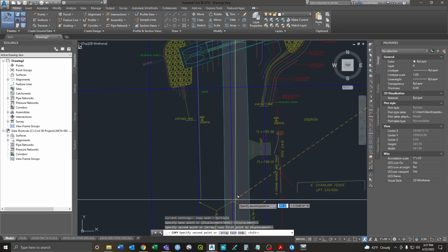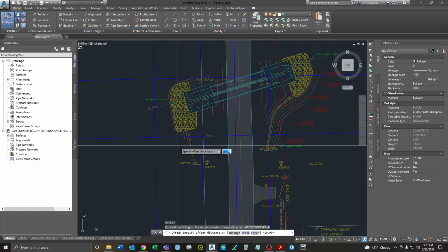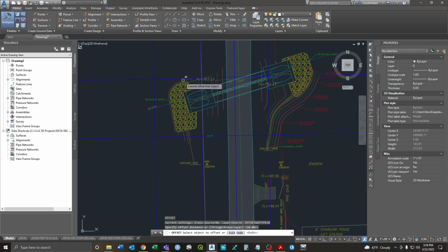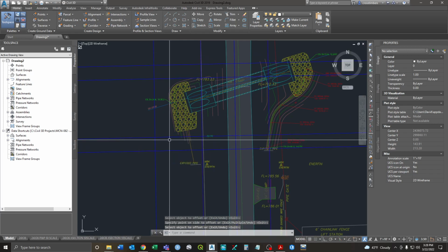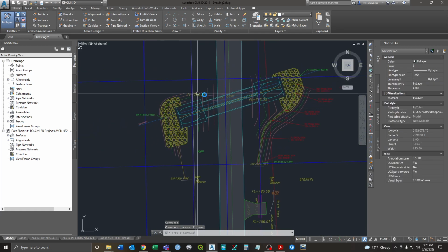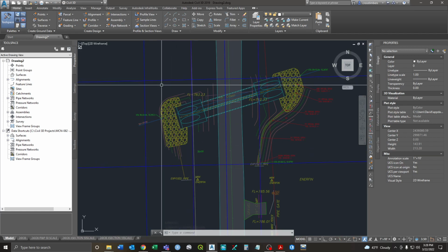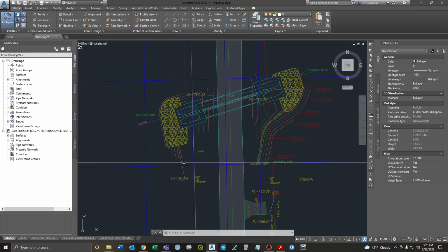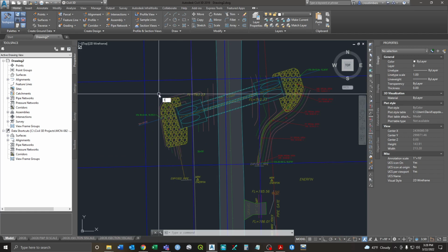So, again, we'll just offset these another 10 feet because we kind of hugged where the edge of the construction was, and then now we're going to put those 10 feet out, and we'll just delete these interior lines. Okay, so now we got a bunch of lines going everywhere. But this square right here is going to be the right-of-way that we want to take. Okay. So we're going to just trim this up.